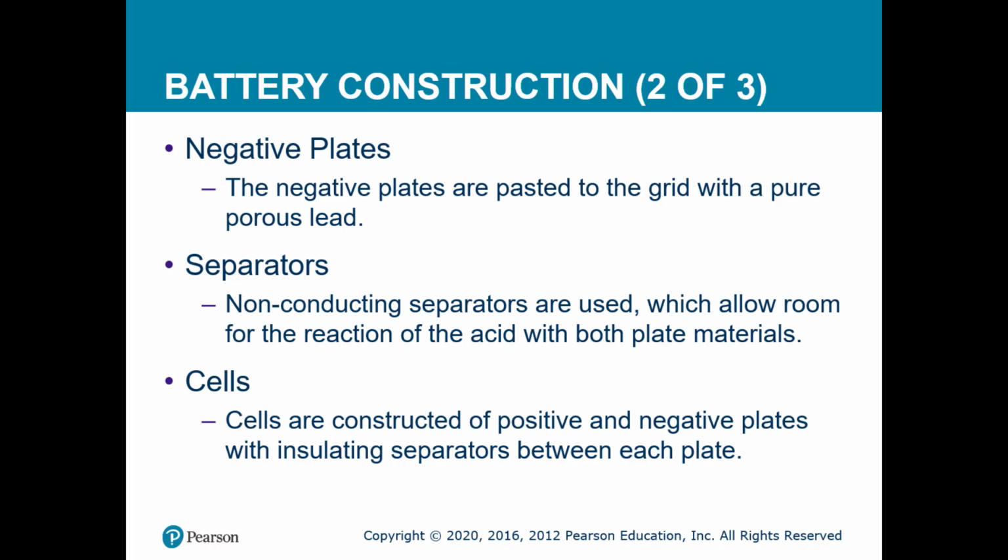Some heavier duty batteries will increase the count by 1, meaning 5 positive and 6 negative. So that would make it 11 plates per cell or 66 plates versus the 54. Whether you have 66 plates or 54 plates, the voltage will remain the same. However, the CCAs will increase. So in other words, the amount of amperage output or the potential for current would increase.